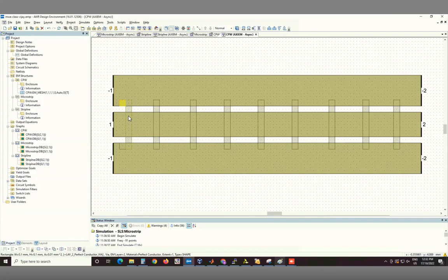See, we are trying to fix the potential of this guy to that guy. That's the purpose of this. Connecting this like this is not going to really make it. It's sort of like, instead of having these strips, I could have had an entire metal plane going all the way across like that. That would be almost like a ground plane.